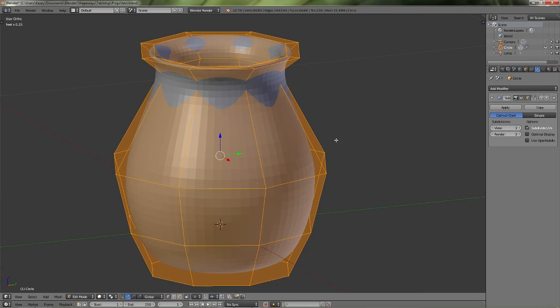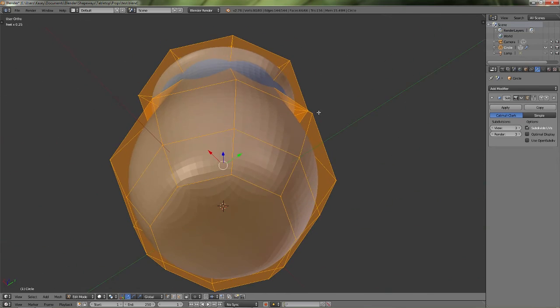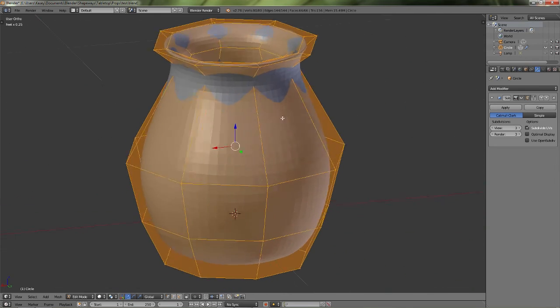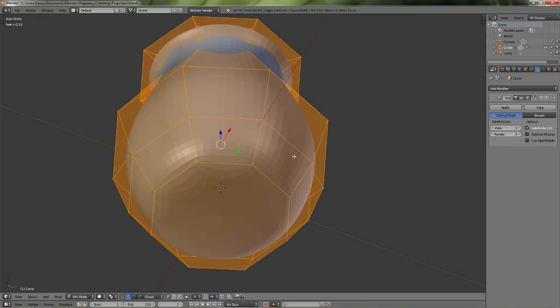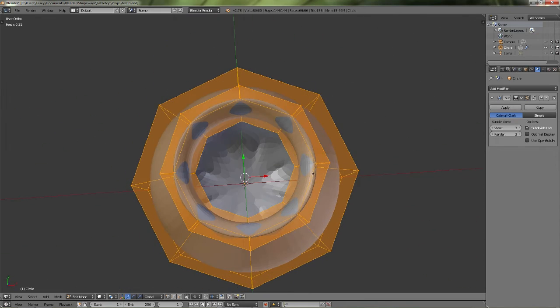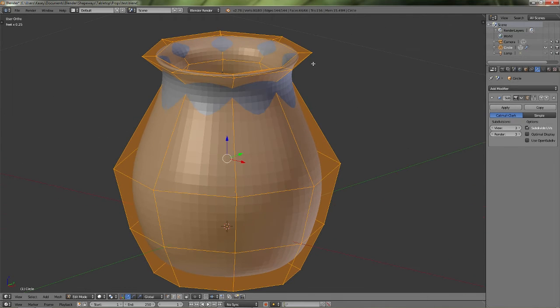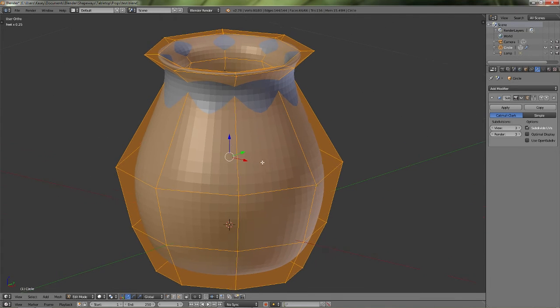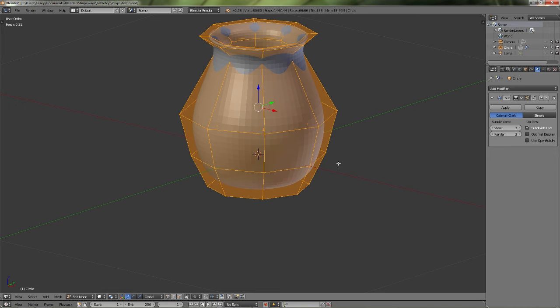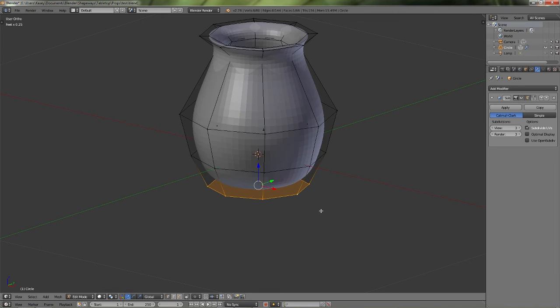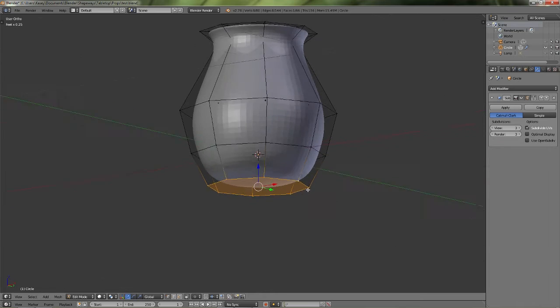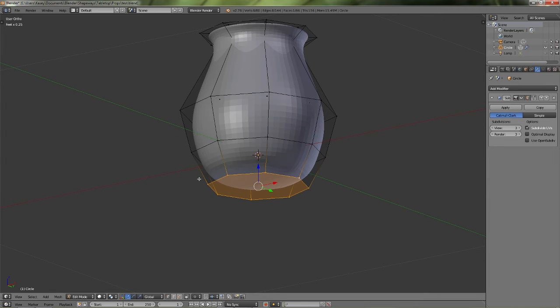Now you notice it also got rid of some of my angles. It's not very flat on the bottom anymore. It gets a little wonky in here. And this lip is probably way too thin to print now. So, ways to fix that. Kind of like we did before, Alt right click this bottom, because I want this bottom to be completely flat and have a sharp edge.